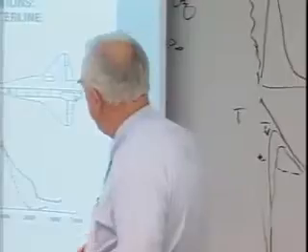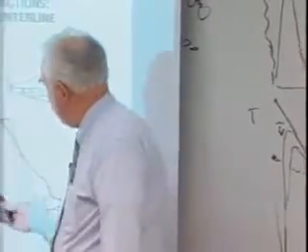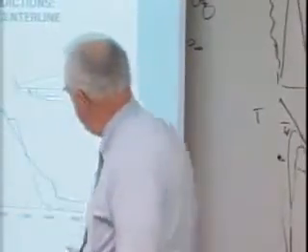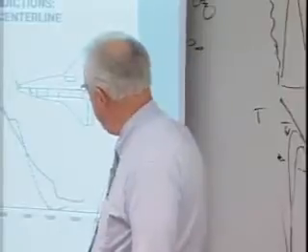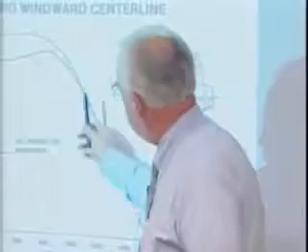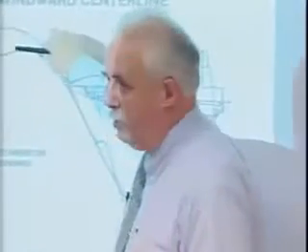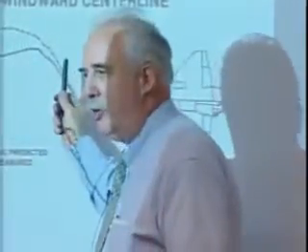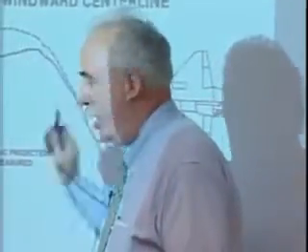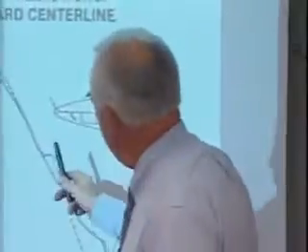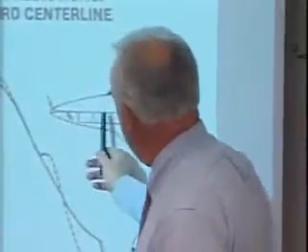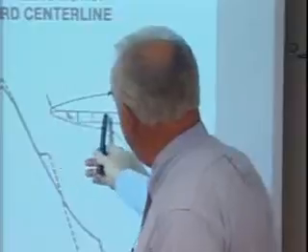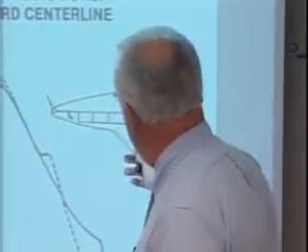Okay, now I'm going to show results in terms of temperature as a function of time. This is the entry time from about 400 to 1,000 seconds. You notice this plateau. You're talking about 20 minutes entry and 10 minutes of flying it so you don't exceed the thermal protection system. Okay? I'm going to show 3 locations. Right up here at the nose, just behind the carbon, mid-body, and aft-body.